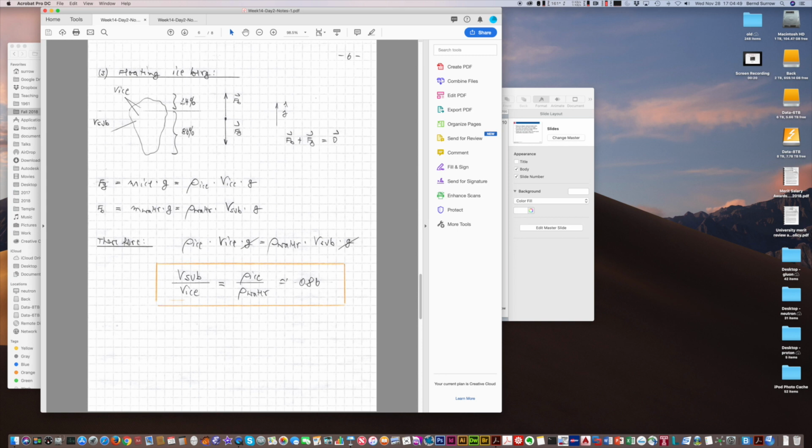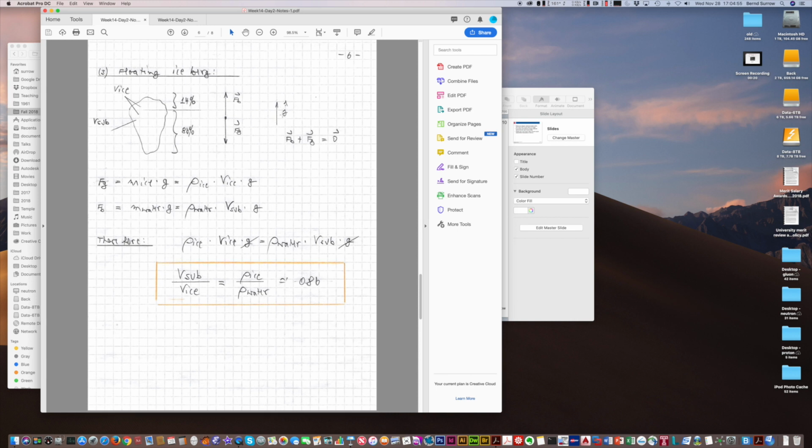So let's take the unit vector direction again here, upward. The buoyancy force is upward by the amount of water displaced by the frozen ice, plus Fg here. So Fg is the mass of this ice times g. Mass I replace as the total volume times the density of ice.